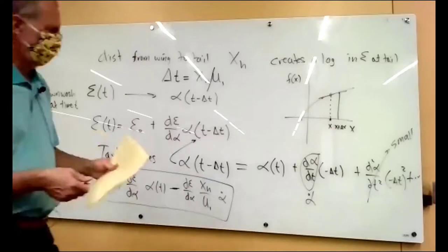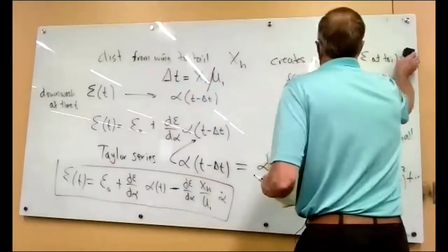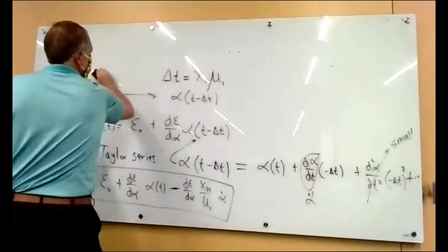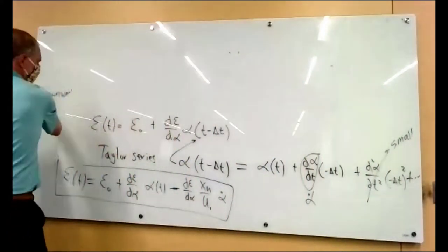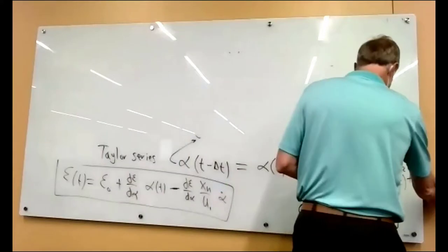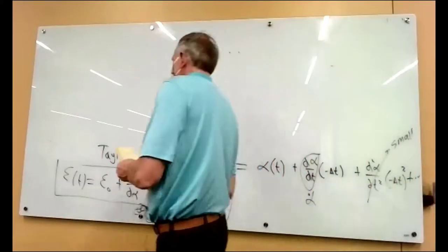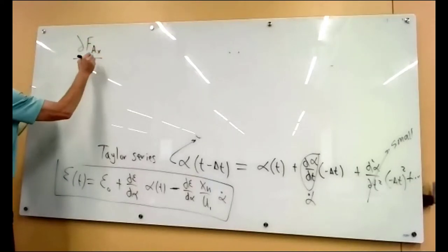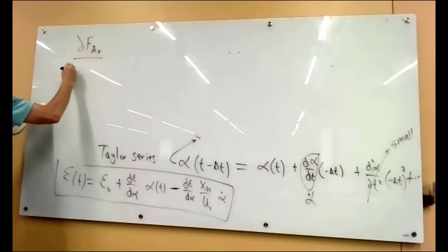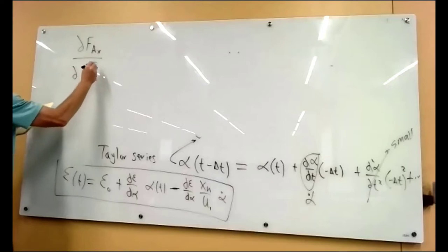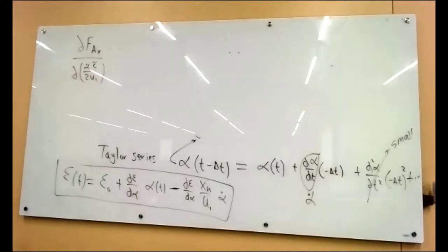So now we go back, and we're going to use this in finding out the effect on the drag and the lift and the pitching moment due to alpha dot, because the alpha dot effect is exactly this thing here. So now we go back to what we've been doing. We write an expression for the x force aerodynamic, and we're going to see, well, how does it change with this non-dimensionalized alpha dot? And we know it does now because there's alpha dot in the downwash.